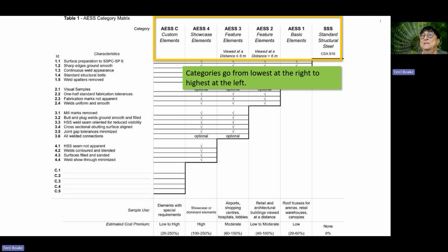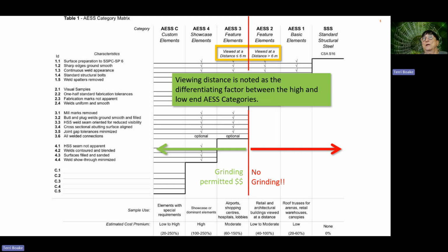This would apply in cases where you'd be using weathering steel, reuse sustainable steel that you want to keep the existing paint coating on, or stainless steel. So one of the things that we were trying to do in designing the system was to make sure that the fabricators were not having to do an undue amount of grinding of the welds, because this costs a lot of money and it delays a project.